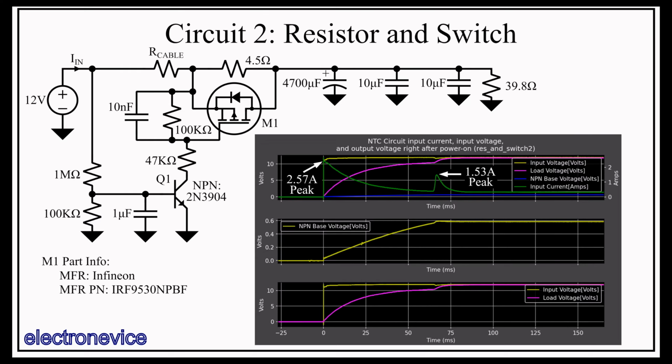This is good for circuits that don't draw a lot of steady-state current or only switch on to higher power modes much later after post-turn-on. However, it does present a difficulty if the circuit always draws lots of power. The thermistor got around this by slowly changing its resistance over the course of several seconds, which slowly charged the capacitance and didn't cause a secondary surge current. You can replace the series resistance in this circuit with a thermistor.